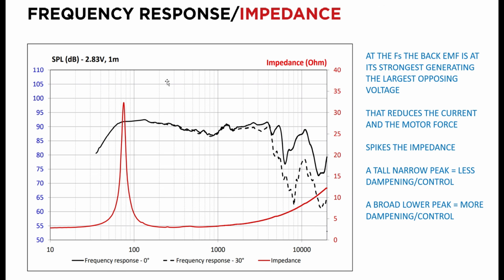And that means that the voice coil is bouncing up and down with its maximum excursion, right? And when it's doing that, and there's not a lot of force being applied electrically by the motor because the system wants to swing naturally, then you create a lot of back EMF, and that's why you get a massive peak in the impedance, right? This impedance curve, there it is, and that's the way to tell where your speaker's FS is, because the voice coil produces a big peak.